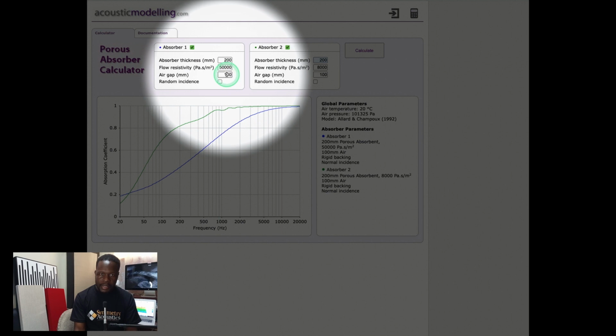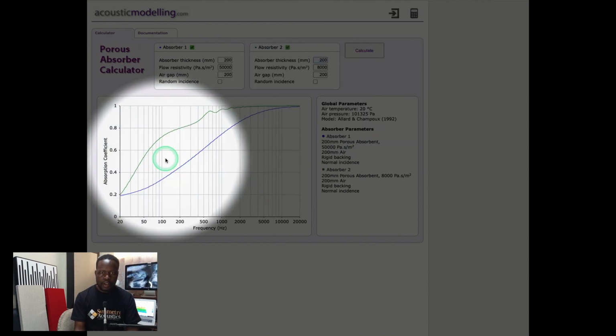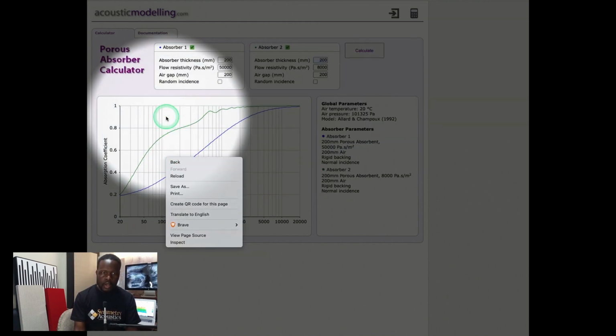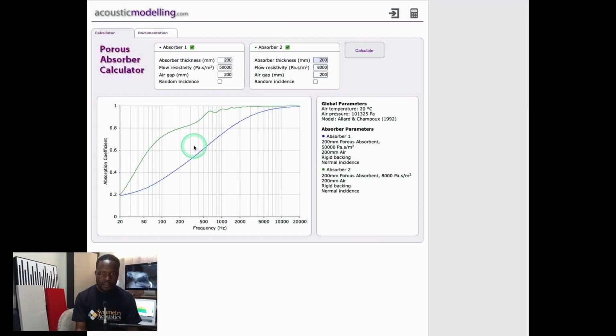Actually, it's not even a bass trap. It's still not absorbing even enough of the lower mids below 500 hertz. So basically, the 20 centimeter rock wool panel does the same thing that a 4-inch or 3-inch panel of the same material would do. It means we have wastage of material there. The performance is so low. On this other side, look at the fiberglass, the fluffy material. It performs very well towards the lower frequencies, working all the way to around 80 hertz, and you can check that in the diagram there.